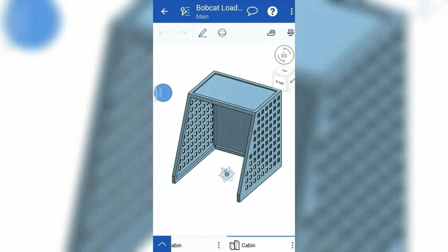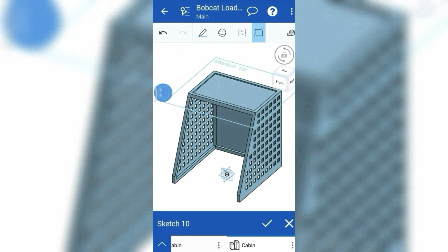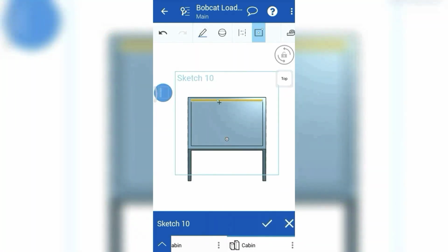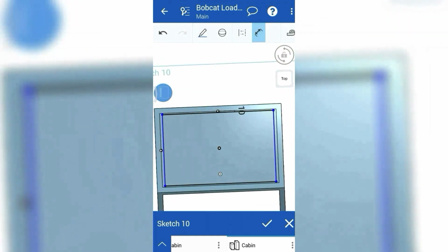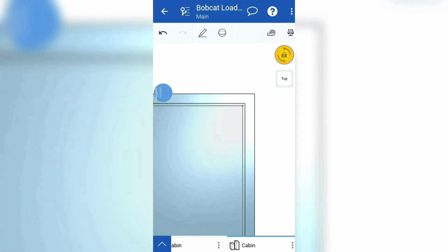To sketch number 10, select the top face and draw a rectangle whose sides are at a distance of 10 mm offset from the edges of face of extrude 3. Go to Extrude Remove feature and remove the region inside the rectangle.